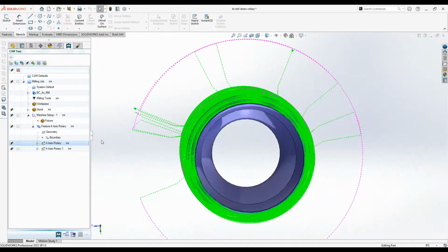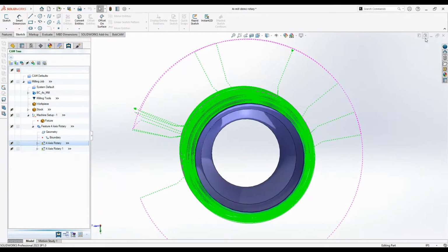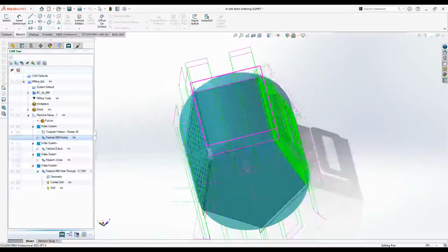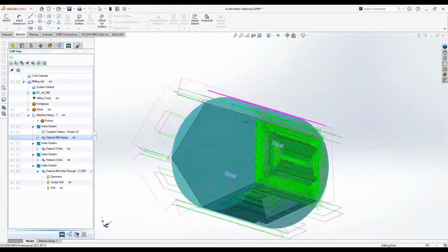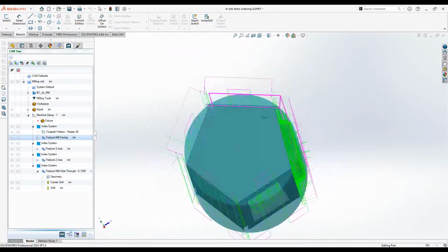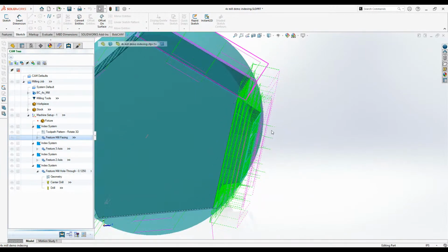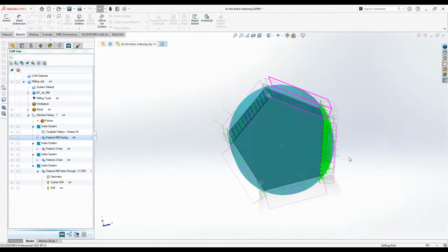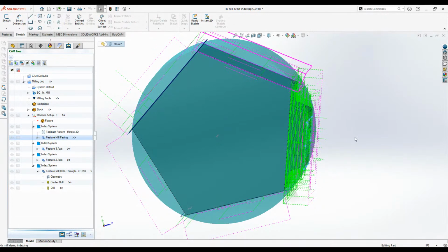So that's the side shift option there. That's under the patterns page to be able to use the side of the end mill a little bit more. And like we were saying, if we wanted to get into using the side of the tool to maybe mill out the top surface here for the end mill, it would basically be setting up an index. So that would take some time to set up an index perpendicular to that surface,